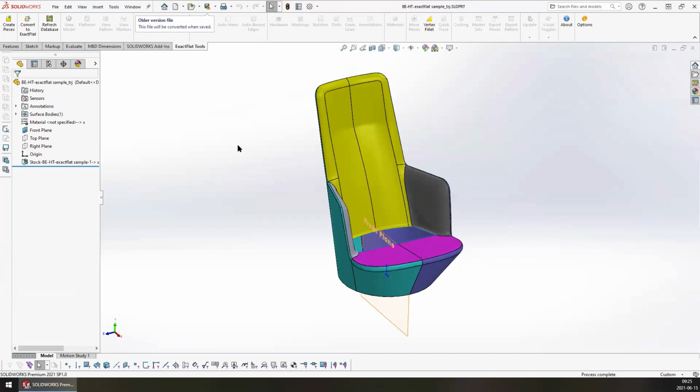If you do realize that you've made a mistake, or you need to add a cut line or a dart, or you need to change the shape of a face or scale your model, you need to basically remove the piece creator from the document. That will effectively undo all of your flattening and patterning work. You can then make a change to your 3D model, and then you can restart the flattening process starting with the piece creator.